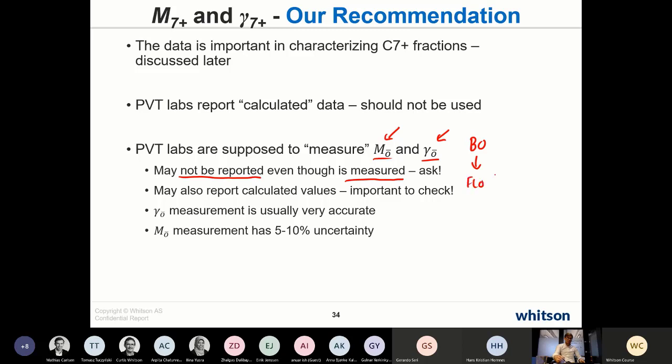In the gas condensate case, it is actually the flashed separator oil. So when they've taken the separator oil and flashed that to stock tank condition, it is essentially just removing the gas that comes out of solution. So that's where you get this data.